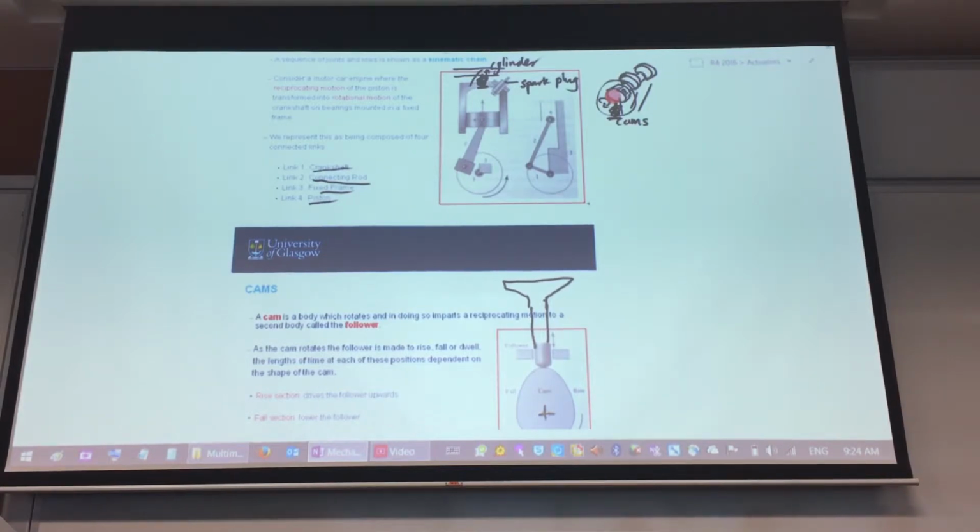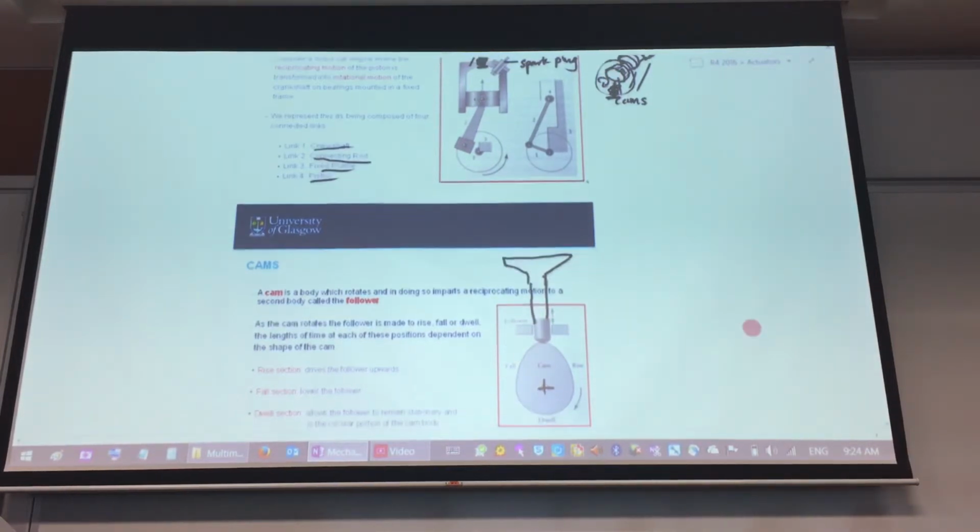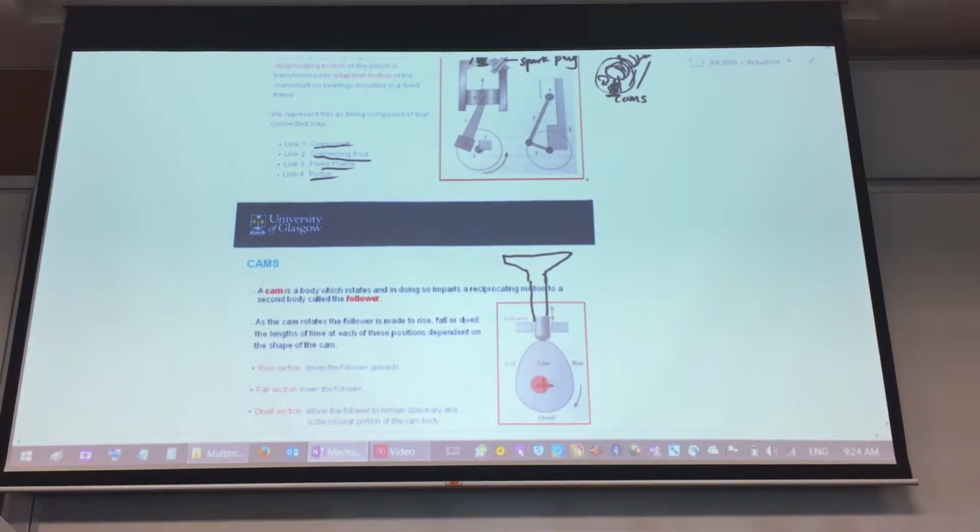So it's actually possible. You have to design it and balance it out so that you don't have an overall excessive vibration due to this amount of offset. Where's the offset? Had it been just a circle in this way, if you rotate this shaft at high speed, no problem. But had it been a little bit that way, where the center of it is a little bit off, if you rotate the shaft, you're going to experience a lot of vibration. So the cam is just like that. It's a little bit off-center.